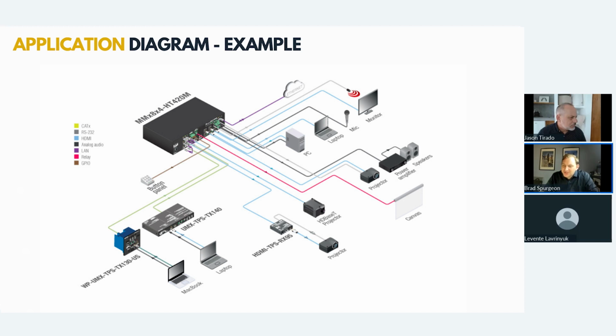And then right next to it, you'll see an HDBaseT projector with the native HDBaseT connections. That might be that Panasonic DigiLink, or it might be an NEC display or some other manufacturer that works with HDBaseT. And then, of course, I have some local sources, and this device does have the ability to take a microphone in and do mic mixing, or tie it into a DSP if you want to do some more complicated sound reinforcement and that sort of stuff. This is a very, very common design that we do often with these 8x4s and some smart extenders, and especially wall plates as well.